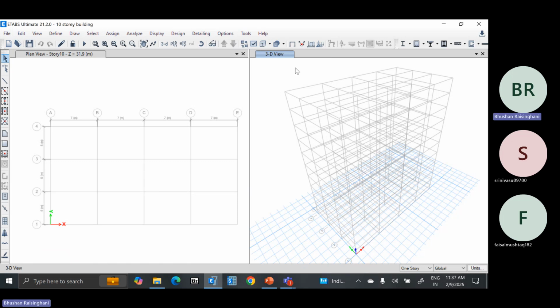Okay. Now this is the extrude view that will convert your line element model into a 3D model. Each element will convert into a 3D object. Then this is the undeformed shape. If you are looking at a model with the shear force, bending moment diagram, reinforcement percentage, or any option in which you have seen some outcome, and you want to again come to the normal state, you can select this option, show the undeformed shape, F4. Either click F4 or click this option.